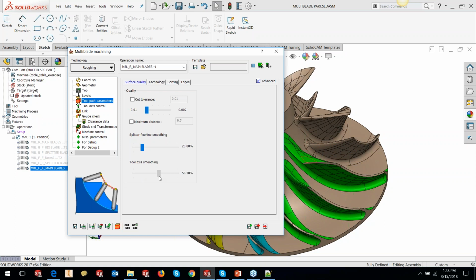I suggest you push it up to, let's say, about 75 and keep it at 75. You'll see that the problem of the C-axis completely rotating every time there's a movement will disappear. Otherwise, 20 looks perfect. You don't have to fiddle with 20. If you don't have any issues with the C-axis rotating, keep it at 20.